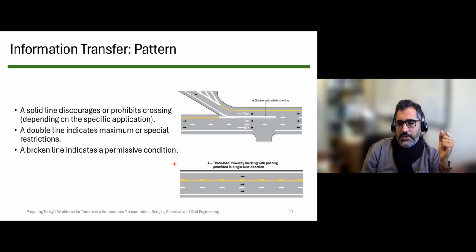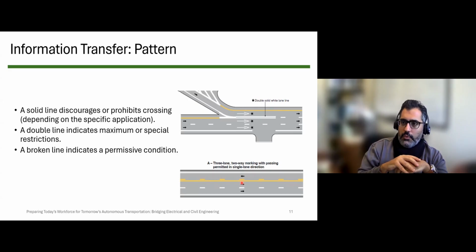Sometimes we just have solid lines, like look at the center line that is solid, and we have broken lines. So the center line includes one solid and one broken. What does that mean? It means that, let's say this is north, then this would be eastbound vehicles moving towards east. Eastbound, they are not allowed to move into the opposing lane, but westbound they are allowed because this is a broken line. Both of them are yellow, which shows the separation of two different directions on one corridor.